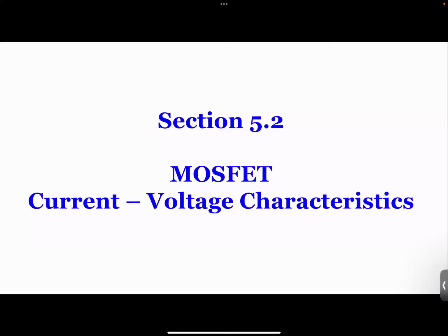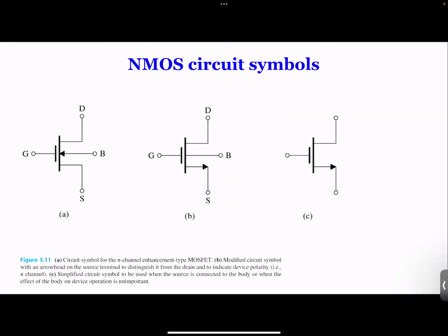But for consistency, we're going to have MOSFETs where the drain is always on top, especially for NMOS. And for PMOS, we already also looked at that, it's just opposite of NMOS. And we also have CMOS, which has a PMOS and an NMOS made on the same substrate. So we are going to start today by looking at the different ways to express an NMOS circuit. And later on, we're going to also talk about PMOS. Today's lecture is more on NMOS voltage and current characteristics.